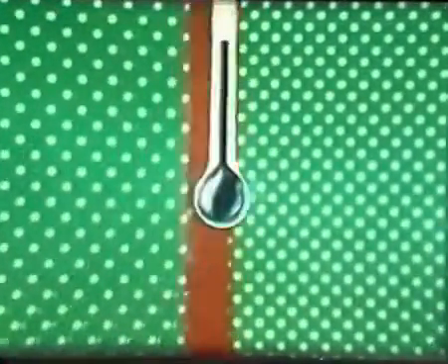A shock wave is a very narrow region, about 1/10,000th of an inch thick. Across this region, the supersonic airflow is violently reduced to subsonic speed. Much of the air's energy of movement, or kinetic energy, is dissipated as heat. The temperature of the air rises suddenly as it passes through the shock wave. There is also a sudden rise in pressure.